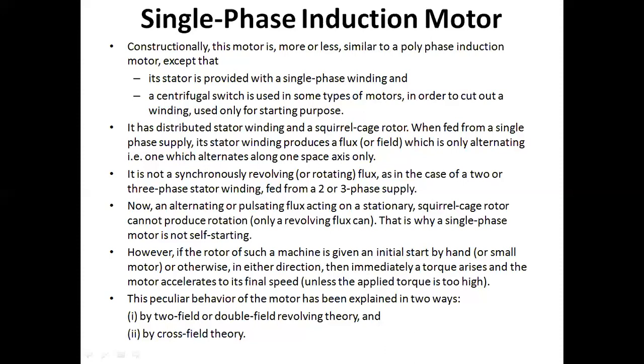Just a small recap of the three-phase induction motor. Three-phase induction motors are self-starting motors. Whenever we give the three-phase supply, there is a rotating magnetic field, and that rotating magnetic field will be able to start the motor. But for the single-phase induction motor, we need to use a separate winding for starting the single-phase motor.